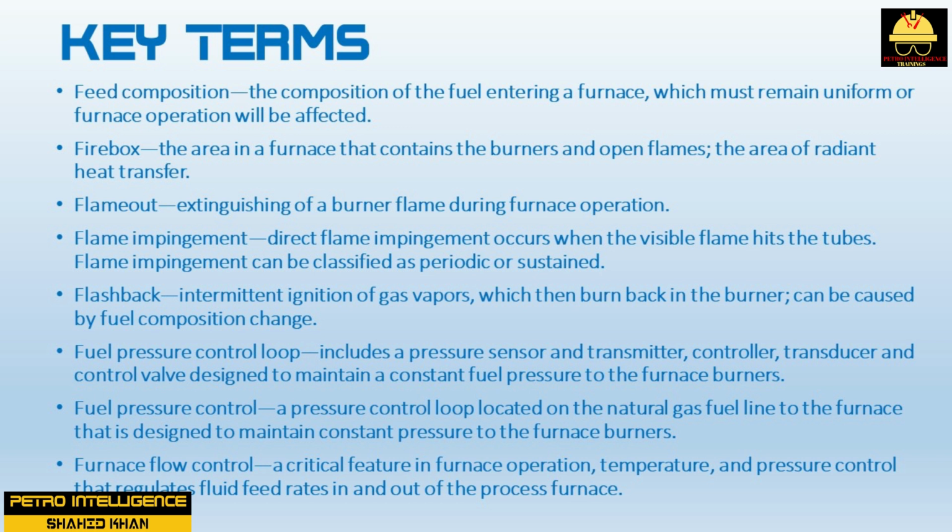Fuel pressure control loop includes a pressure sensor and transmitter, controller, transducer and control valve designed to maintain a constant fuel pressure to the furnace burners. Fuel pressure control is a pressure control loop located on the natural gas fuel line to the furnace that is designed to maintain constant pressure to the furnace burners.